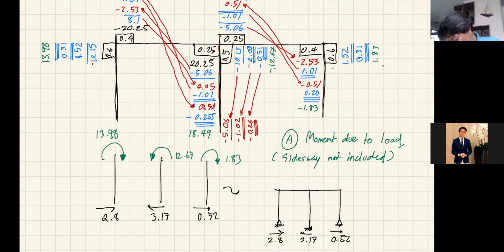And so we have the unbalanced sigma Fx of 0.50. So in other words, I should add the joint here to prevent the side sway, and I will get the reaction equal to 0.15. Okay, so you can say that this is your imaginary load for side sway.